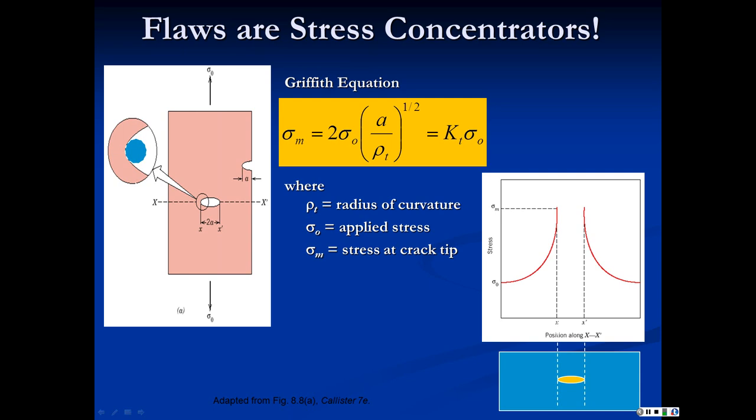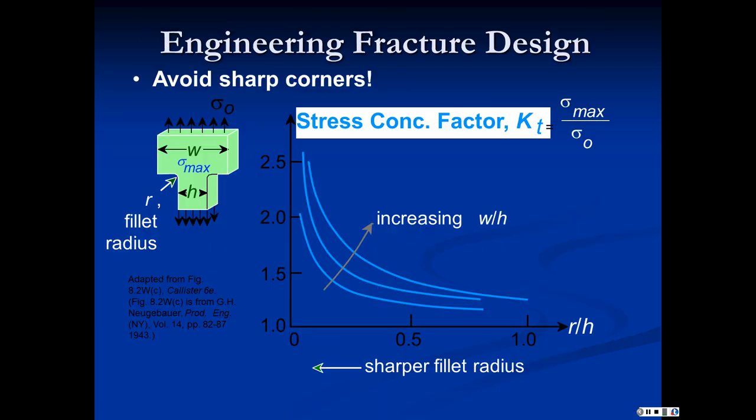And then that stress rises, this 1 over the square root, you'll see in a little bit, 1 over the square root of r, to some peak value, sigma m. Now this is for a finite radius, generally a fairly blunt radius. Okay, and we have that at both tips. Now, that is called the Griffith equation, and a Griffith flaw has that clear radius.